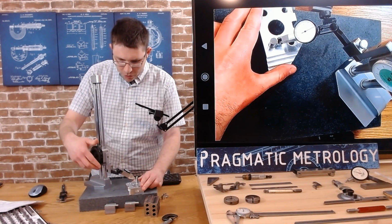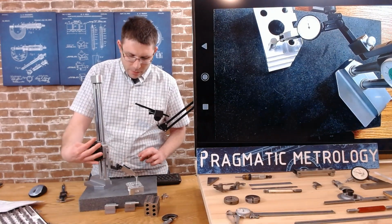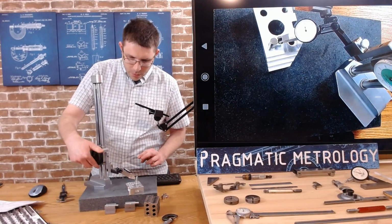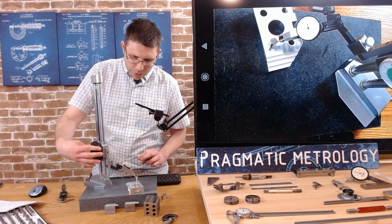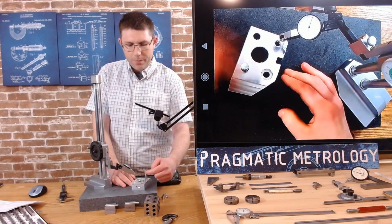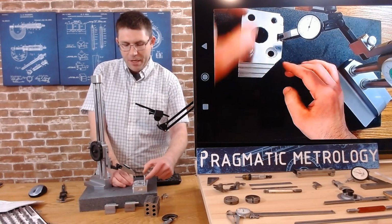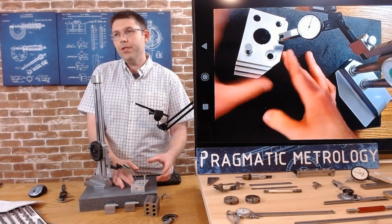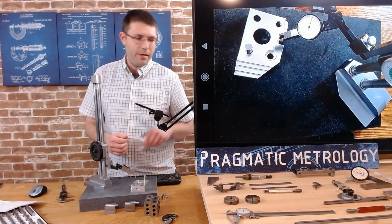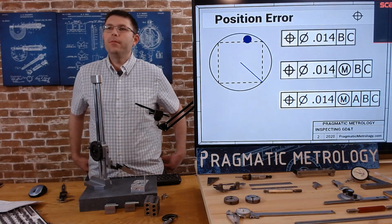You may want to do 2 or 3 orientations depending on how big the hole is, and look for the pin bending one way or another. And again, I get even probably less than a 1/2 thousandths this time, maybe just 1 or 2 tenths. So most of the error is probably in this direction and not as much in this direction. But again, that pin is leaning one way or another, and this is a pretty easy way to check if it's straight and then add that to your 2-dimensional error to get that 3rd component.